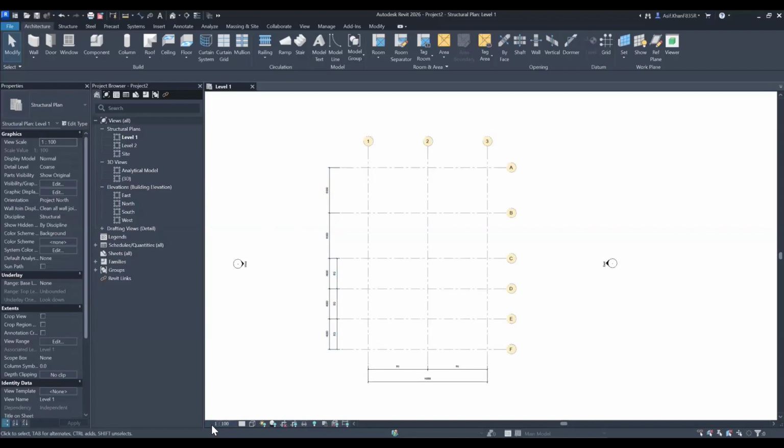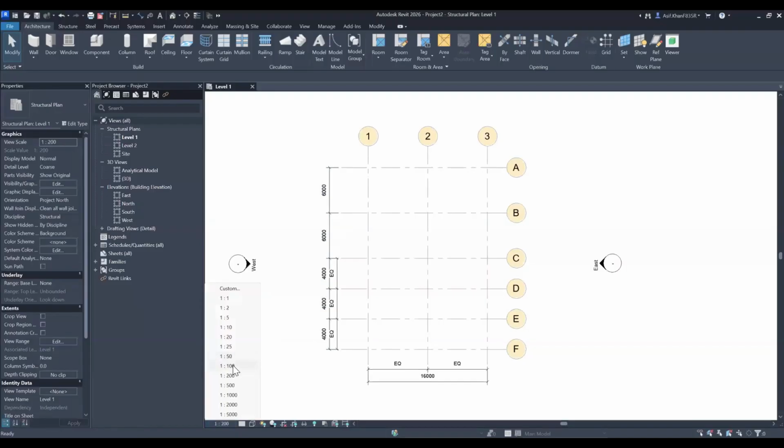Now over here at the bottom corner of this viewport, you will have your annotative scale. If I just change it, say I want to go for the bigger scale, once I click it, it automatically adapts all the annotative elements, just getting smaller. If I go for the smaller scale, everything is getting bigger. Just imagine how cool is that? You don't have to assign anything, no line work, no nothing, no texting. Just select, click, 2 clicks, grid done, dimension spaced out with the editing of the dimensions, and just so flexible to work with.